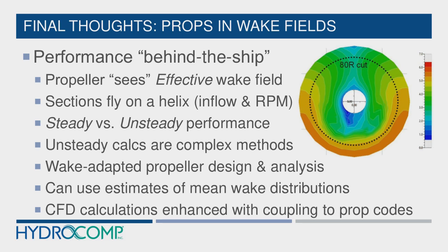It needs to be more than a handful of cells in the grid, because there's local shear effects if it's too close to the propeller that we want to avoid, but not too far upstream that we have to correct for the difference, which we can do, but it's just another slight uncertainty because you have contraction in the jet stream, and we're trying to go from an upstream disk area into a propeller disk.